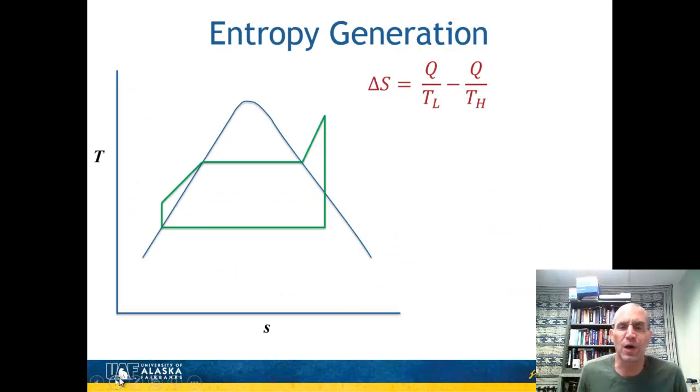All right, so first I want to talk a little bit about why feed water heaters are more efficient, how they increase the efficiency, and it helps to understand that in terms of entropy generation going on in the Rankine cycle. So what I have drawn on this diagram in green here is the simple Rankine cycle where we have 4 points. This would be the outlet from the condenser, traditionally point 4, inlet to the condenser at point 1, and then the boiler is points 2 to 3.